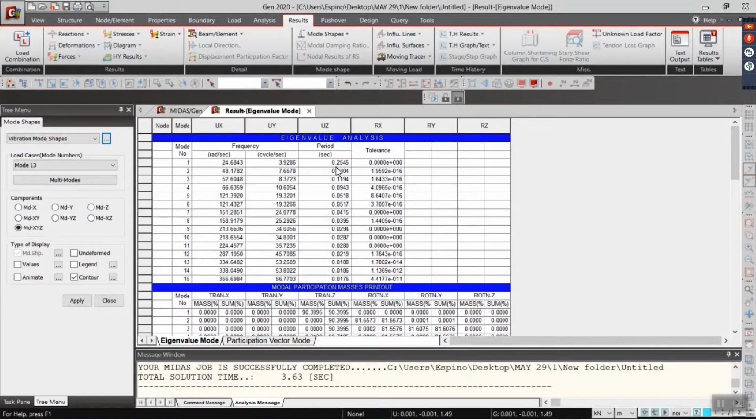So approximately around 0.1 to 0.5 seconds, if we have this period in our floor structural system, we can call it, I don't want to use the term safe, I can use the term within the acceptable limit.